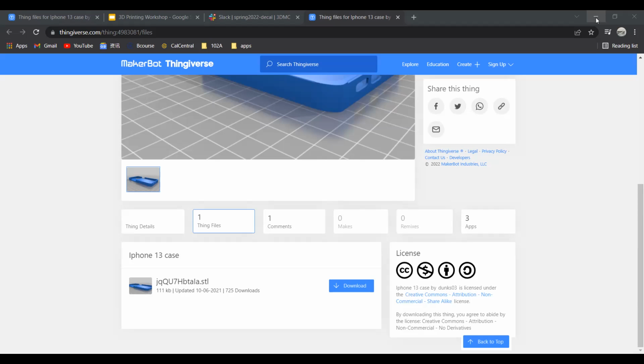So to convert the mesh to a solid body in Fusion, you can generate face groups first, and then convert it. So first we will click this and just leave all the settings, choose the accurate one, click OK.